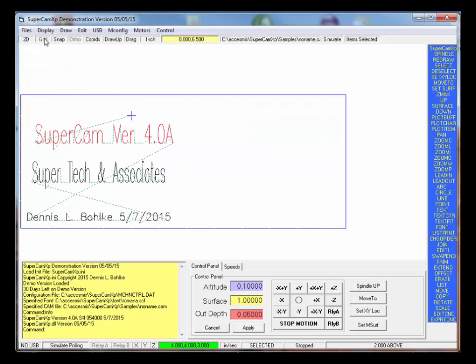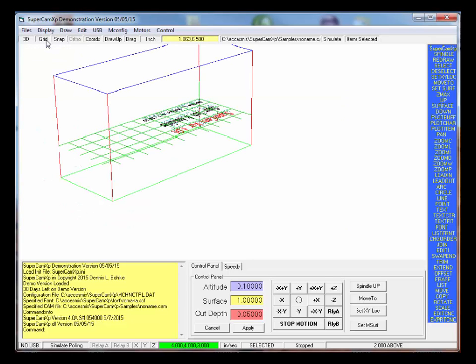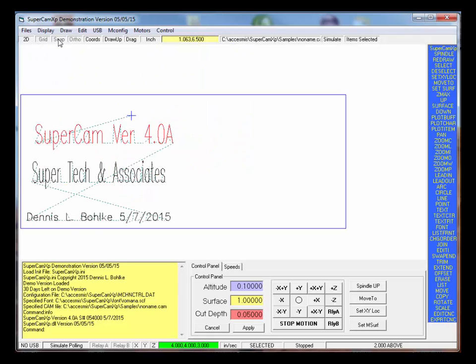This panel turns the grid on and off, which apparently isn't on. If I go into there, I'm turning off the 3D grid. This is snap. That's when I'm drawing a line, it determines a snap. Ortho, coordinates mode, that sets the different panel.